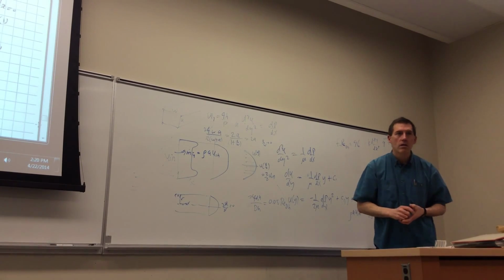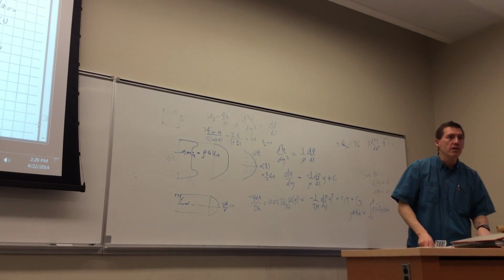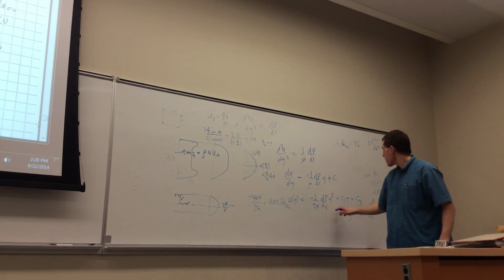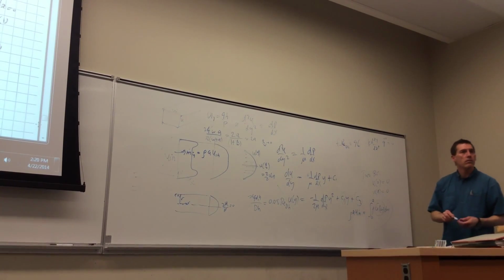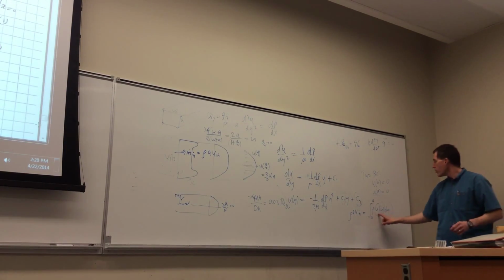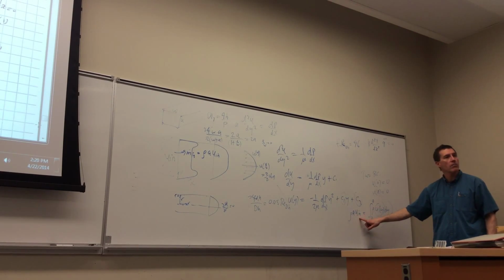So this one was asking for U mean and T mean, given U(y), T(y). So you use the integration, yeah. Because you've got the U(y) profile, and you just integrate it, and you say that's rho times the height times the U mean. So you can get U mean from that.